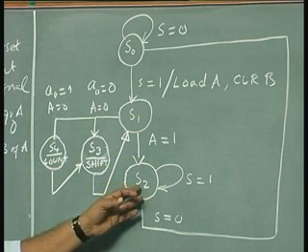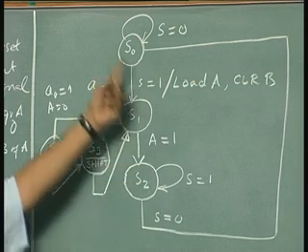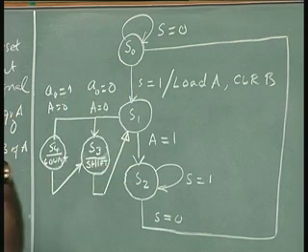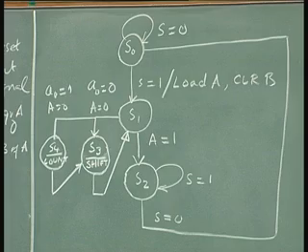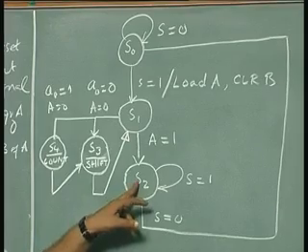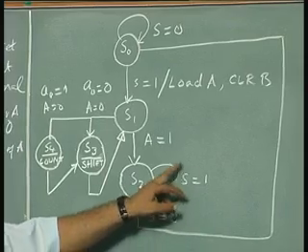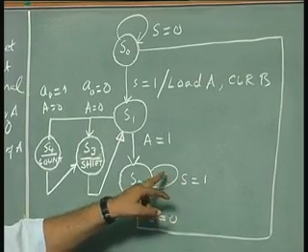But before doing so, I can directly go back and wait for the next start, but I do not know whether the earlier start has been removed. So, in order to do that, I am introducing an extra state called S2, in which I will wait if S continues to be 1. When S becomes 0, I return.